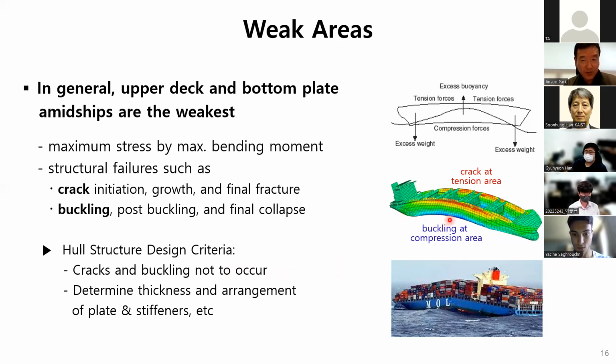This right side figure shows a hogging deformation of ship under a big hogging wave. A middle part bent upward. Stresses in upper deck are tensile, very high, red color. I mean, elongation happens, possibly inducing cracks. By the way, very high stress in bottom. They are compressive, blue color, possibly inducing buckling by compression.